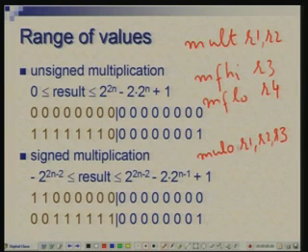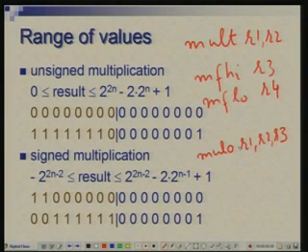Sorry, in this case result R 2 R 3 operand, result is going to R 1. So, we are looking at only n bits of the result and ignoring the higher n bits. So, if the product is bigger than that, if it requires more than n bits, then it is a case of overflow. All right. So, this is the exact description of these instructions.